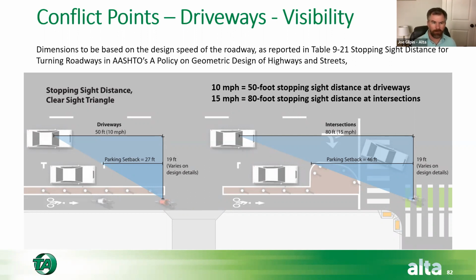So if you do have a lot of parking and you're considering putting a class 4 in and you have a lot of driveways, you may find that there's not a whole lot of parking that remains afterwards. And then I begin to think, okay, well, if we're losing 40 to 80% of our parking by putting this facility in, is that the best facility? And then B, what if we just went to no parking?